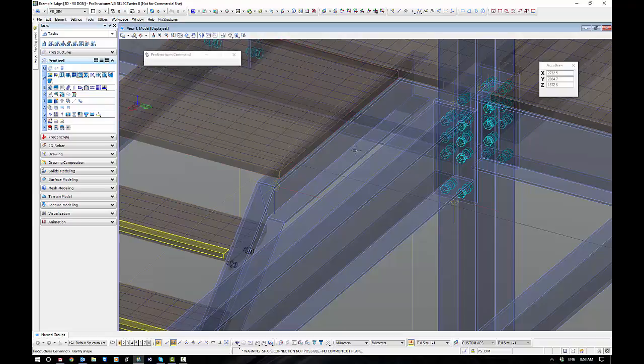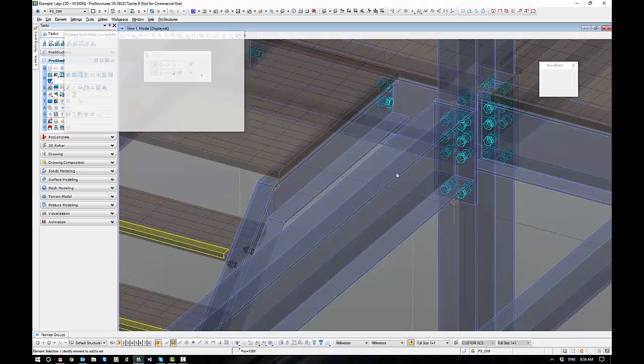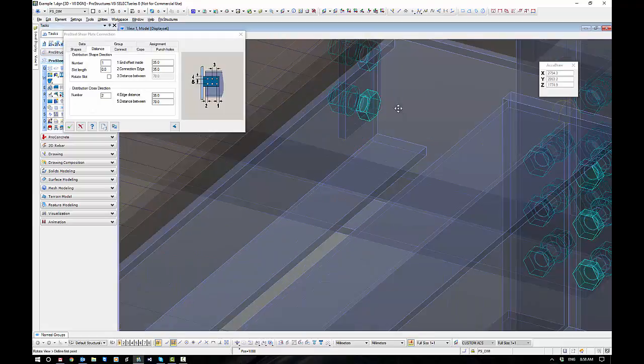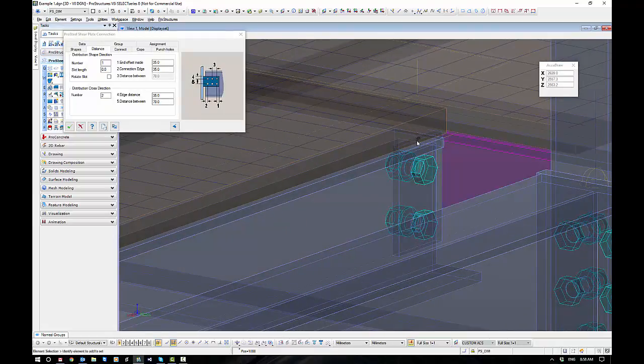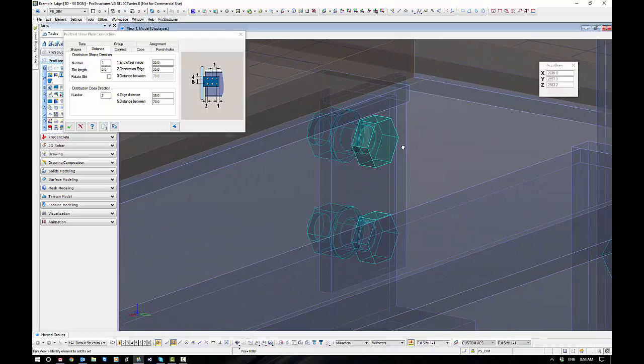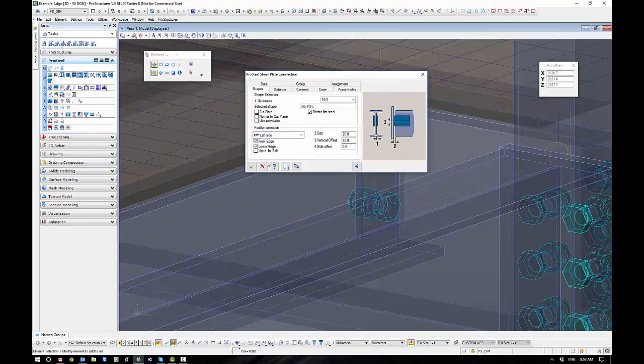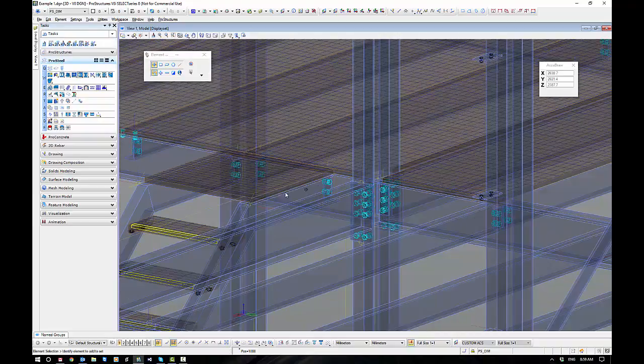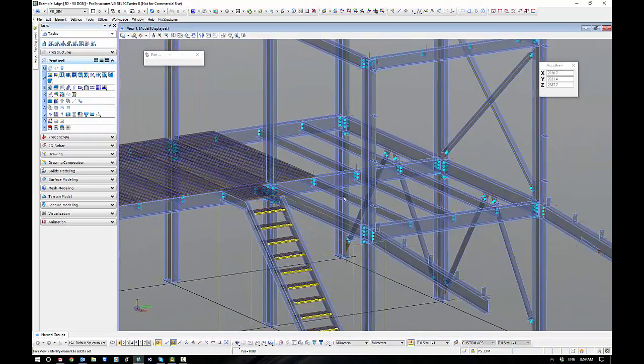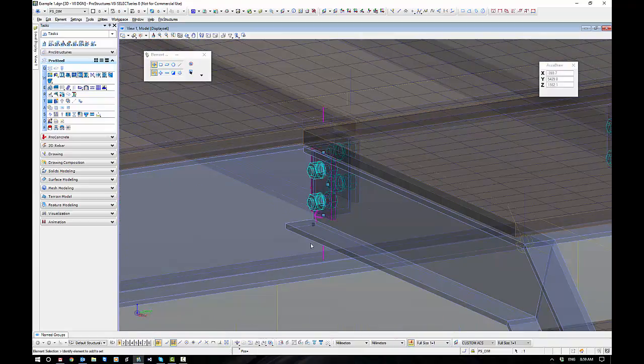Have another go at that. Supported to supporting. The top of steel is actually the underside, which means this cleat here is actually going to be too high. I don't know whether you can make that out. It's a little bit too high there. So if you set this to the lower edge, it means that the cleat is going to come down. Technically it's gone from top of steel to, that'll be 70 mil there. I know this is a little bit weird, but this is a workaround for what we've got to do with the stairs.